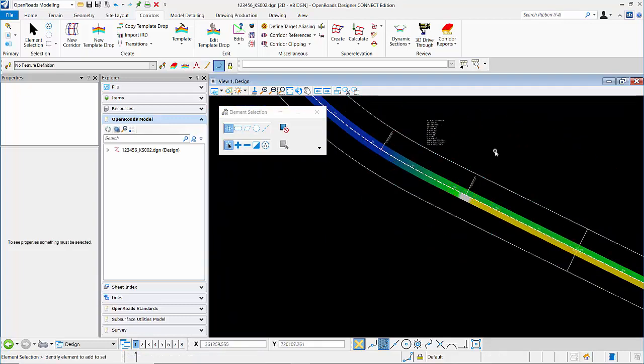So that's just an alternate way to define your superelevation, import it, and assign it to your lanes. If you'd like to use that rather than using the ODOT tables to compute it, this is advantageous, as it allows you to compute the values ahead of time, put them in a CSV file, and then just import those values.